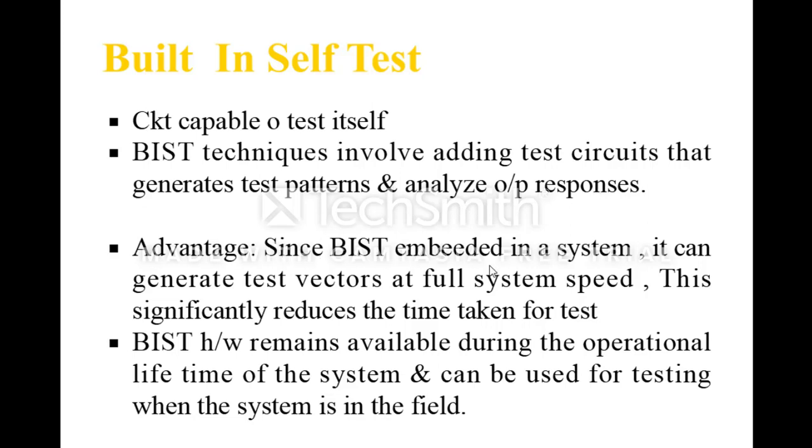The advantage of BIST: since BIST is embedded in a system, it can generate test vectors at full system speed. This significantly reduces the time taken for test. BIST hardware remains available during the operational lifetime of the system and can be used for testing whenever the system is in the field. These are the advantages of BIST.